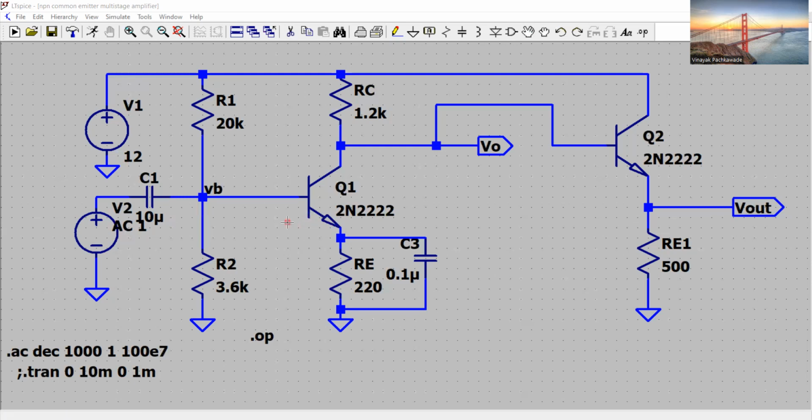And this circuit is potentially uninfluenced by the intrinsic parameter variations of the transistor, which can vary due to the temperature effect. For example, the transconductance of the transistor is a function of temperature. So putting in the emitter resistance, which is also called the emitter degeneration resistance, helps us to get rid of the transconductance involvement in the final gain expression.